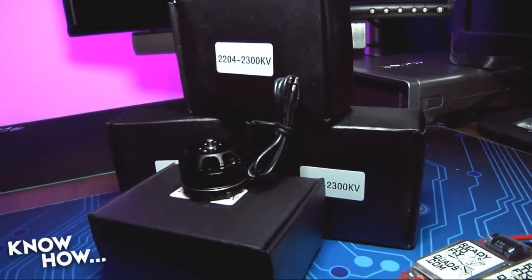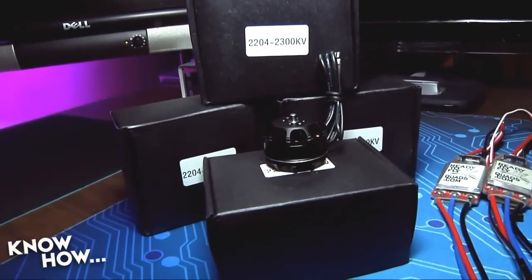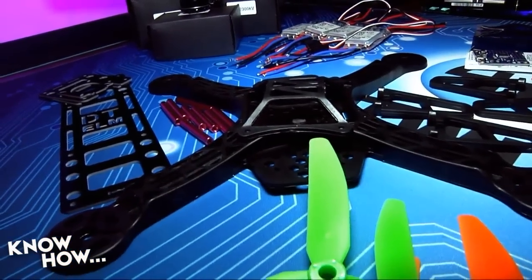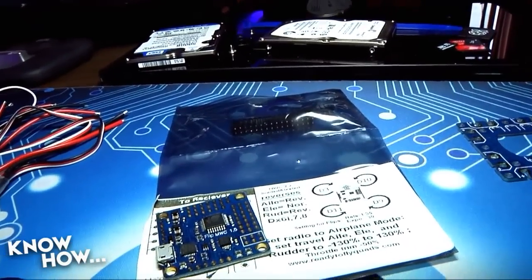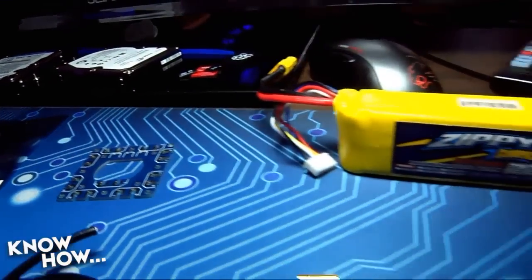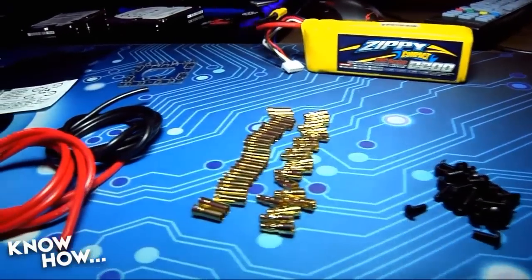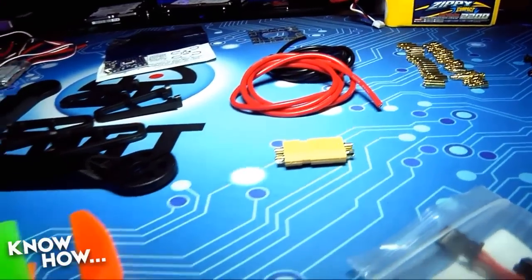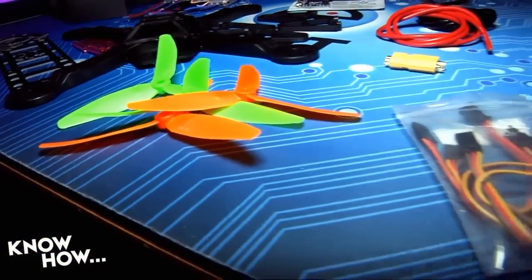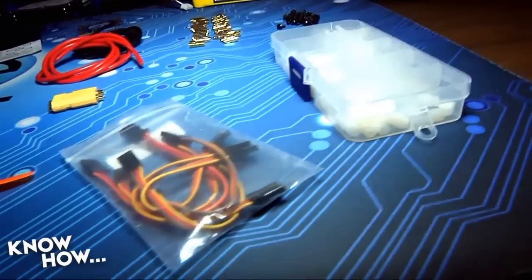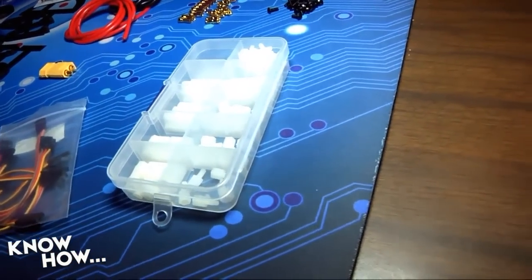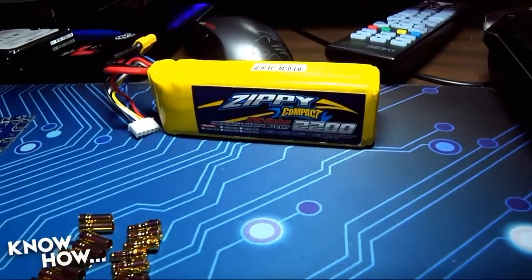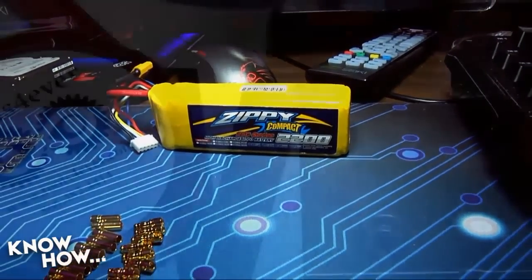To complete our build, you'll need 4 2204 or 2208 2300 kV motors or better, 4 30-amp ESCs, a 250 or 260 class frame with an extension body, a flip MWC flight controller, 45mm power distribution board, 20 pairs of 3.5mm bullets, 1 foot of red 14-gauge silicone wire, 1 foot of black 14-gauge silicone wire, 1 pair of XT60 connectors, 1 full set of 5x3x3 props, 1 set of radio and receiver leads, 1 box of nylon standoffs, 4 M3 12mm screws, and 1 3S or 4S 1000 mAh to 2200 mAh LiPo battery, 20 to 60C discharge.